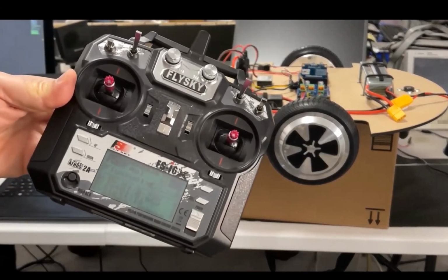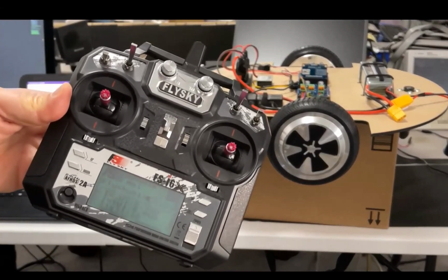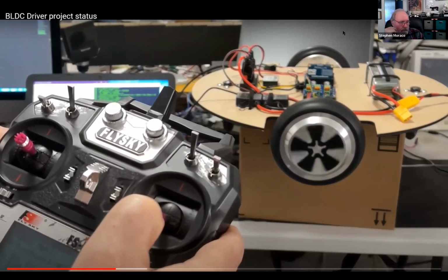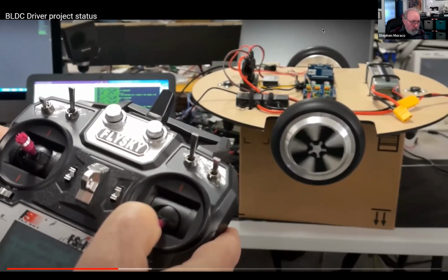Okay, so now I'm going to be using this. I can't keep it in frame, but I can show you that I'm driving the motors. You can hear them being driven. You can hear the ramping up. The frame rate's a little slow here, not quite what I want it to be right now. There's too much torque. That's the noise you're hearing when I slow down. So I've got some improvement to make on the internal ramps. There will likely be external control of the ramps, but the internal ones right now could be improved.